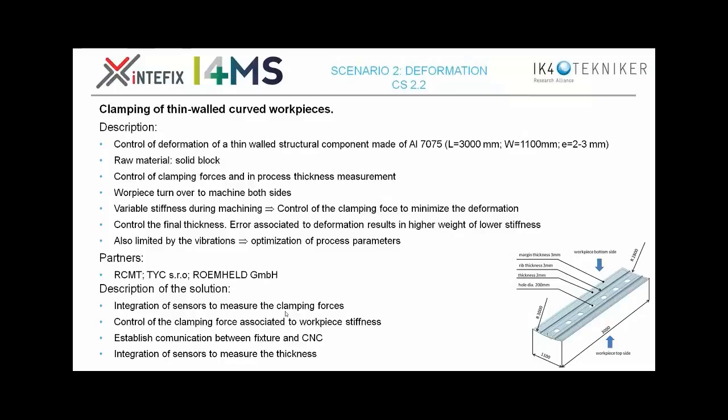As the process progresses, the material removal produces workpiece stiffness change, and the idea is to control this stiffness in order to set the new conditions and the new clamping forces and positions.